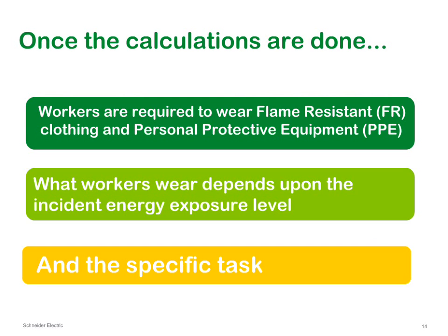At that point we're looking at, for example, what we were talking about here, the worker working on a motor control center, a task that he considered to be something he's allowed to do because it was a troubleshooting action that could not be performed with the equipment de-energized. However, if that action could be performed with the equipment de-energized, he should de-energize the equipment. So he has to be concerned about the task, and he has to be concerned about the energy level that he's going to be dealing with.